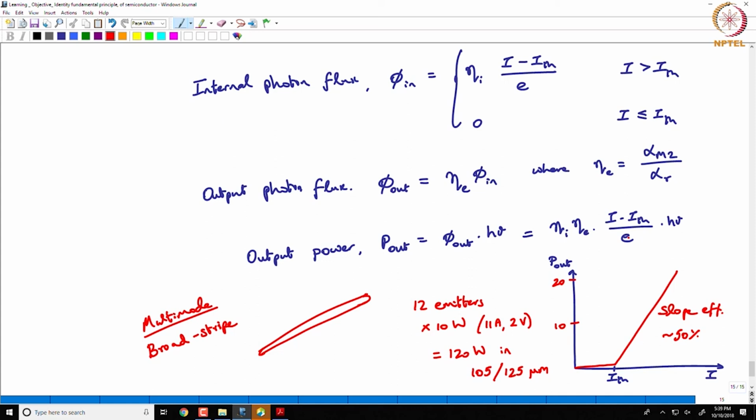But one thing maybe I will mention is there is a specific class of laser known as DFB laser, wherein if this is my active layer, I put some perturbation along this, and let us say my perturbation is such that this capital lambda, the period of that perturbation, provides reflectivity at a particular wavelength called the Bragg wavelength.